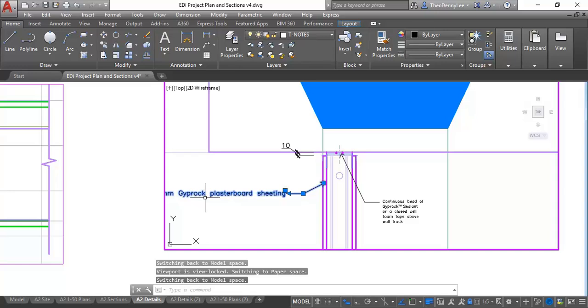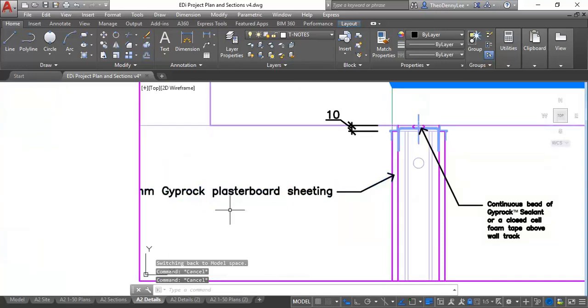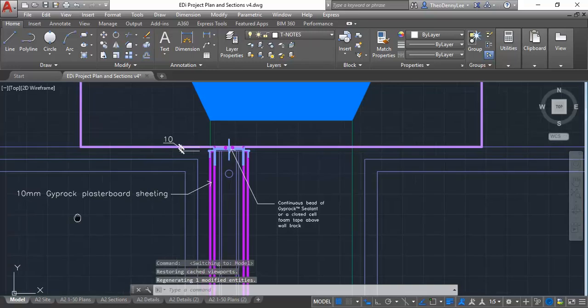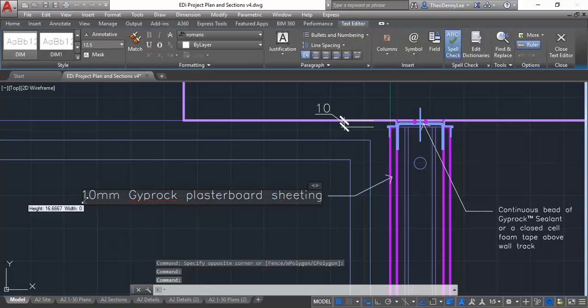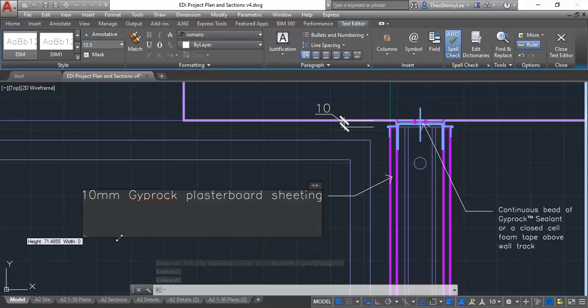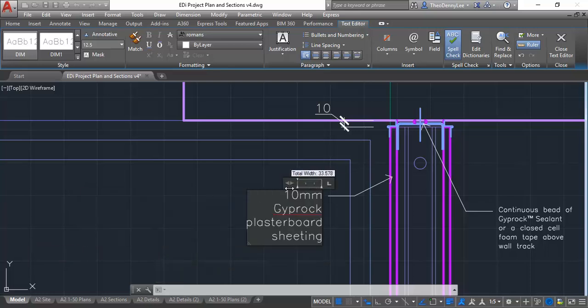But you can see already why it might help to go back. You're drawing in model space, but from paper space, that's right. So I'm drawing on the page, on the layout. But already I've got an issue because I can't see outside the viewport. But I know I can easily switch back to here. There's the text I've just made, and I can just adjust it the way I've shown you just then. Sometimes it's a bit tricky with this. You've got to use a bit of trial and error, but it will eventually let you.